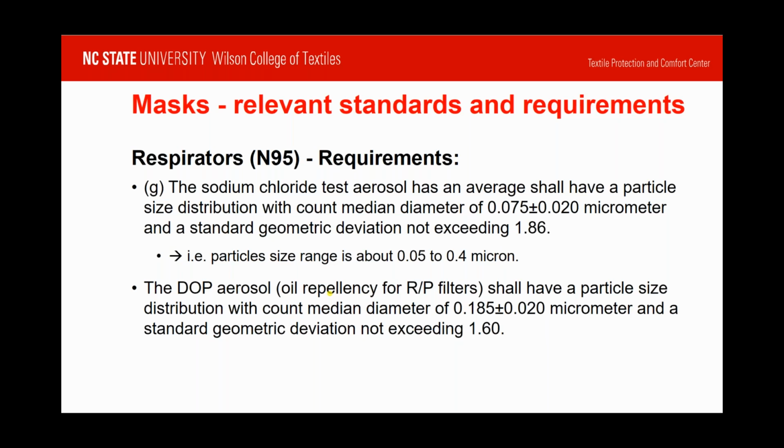So it is not only looking at sizes of bacteria and viruses and small particles that might be detrimental to human health, but it's also looking at the most relevant particle filters where they are having the hardest technical challenges to deal with these sizes, and that would typically be in this range. So that term of most penetrating particle size, which is usually around 0.3 micron, is also in this range.